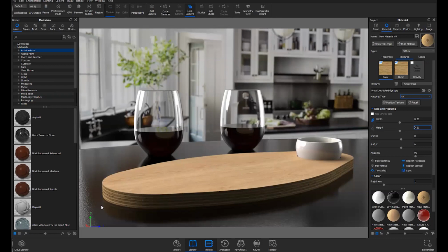And the less seams you have, the easier it's going to be to have your material meet up flawlessly, because there's a seam that's actually right along the front here, but it's nearly imperceptible. I can't actually see it from here. Having less seams makes it a lot easier, especially when the UVs wrap entirely around it, because the program automatically kind of realizes that it's one component.